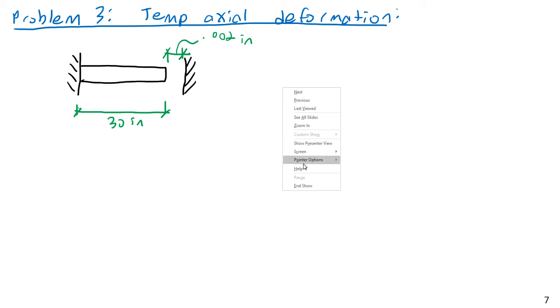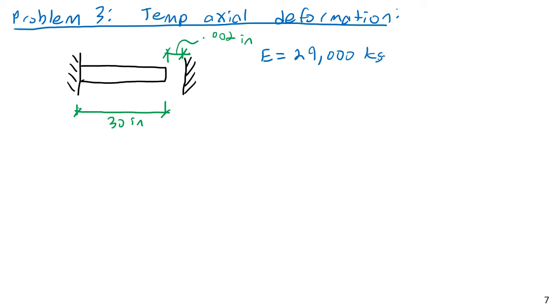So then E, the modulus of elasticity, is 29,000 KSI. And the coefficient of thermal expansion, alpha T, is 6.6 times 10 to the negative 6 inches per inch degree Fahrenheit. In other words, strain per degree Fahrenheit. And so I'm just going to calculate the stress for a series of cases. So A, determine normal stress.